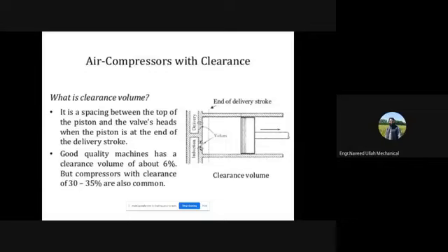So the one that is practical and it is mostly achievable is to change the process from polytropic to isothermal, and that's the way you can get the minimum work, okay, and that is depicted and explained in example 3, where previously for the same data and for the same pressure ratio, the work consumed by the compressor is calculated, and then the isothermal work is calculated, and then they found out that the isothermal process, the work consumed is less as opposed to the one that we calculated earlier for polytropic process, and we will be having some isothermal efficiency. That's it. Right.